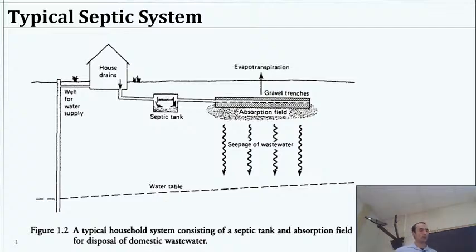Most of that is to protect the drain field so that as we send the liquid out, we have a way for it to disperse without clogging up all the little pores in the soil. And any other constraints physically, we are trying to just simply avoid things like roots growing into that. We'd also make sure that erosion doesn't kind of cut through and expose the field directly, so then you're getting surface runoff or anything like that.